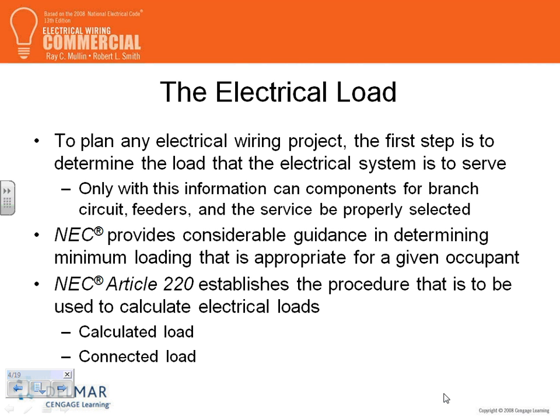So that's how you derate them. If you don't know the receptacle load for a commercial building, what's the assumption? If you don't know the receptacles yet that you're going to be installing, the code allows you to use 1 volt amp per square foot for the building, just to start.